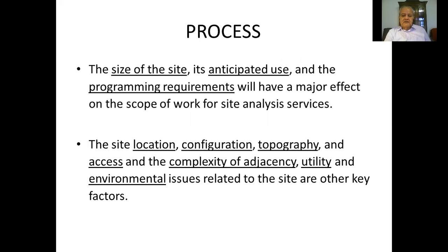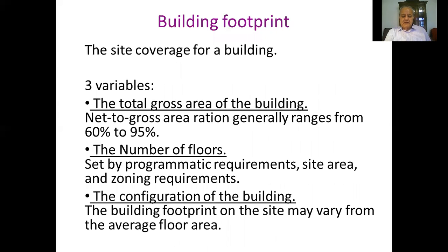So the first thing that you do is that you select the site, of appropriate size, depending on the use and the program requirements. So that's why we start with the program analysis in order to understand how much site do we need. The site location, configuration, topography, access, and any adjacent environments or buildings or utilities around the site.